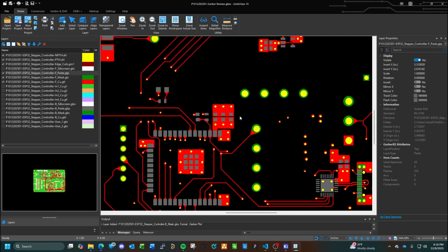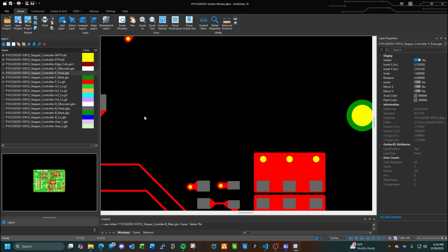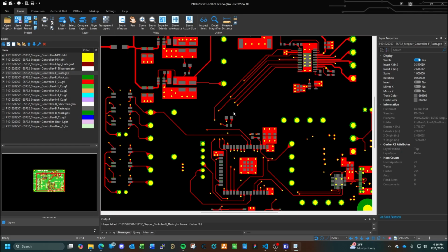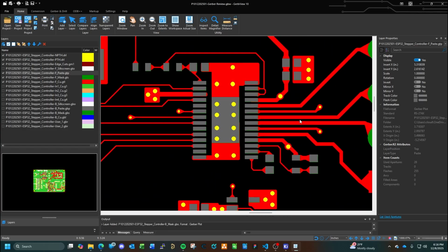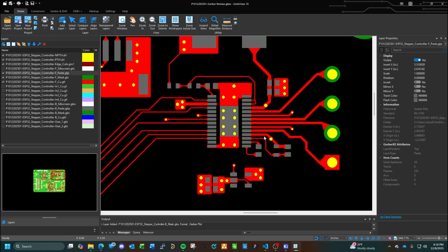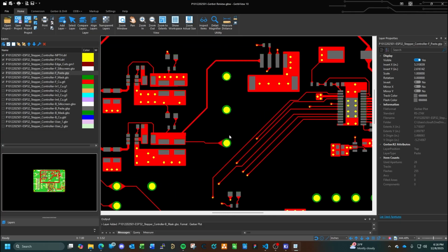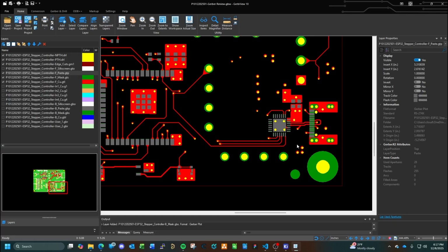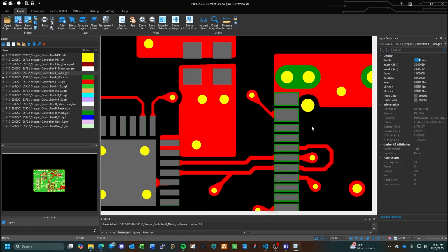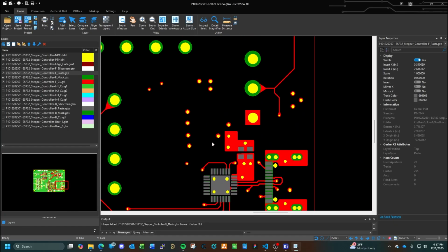So when you get the stencil, it'll be basically a flat sheet of metal. Think of it like really thin sheet metal, and these are going to be laser cut openings. That's where the paste is going to be placed. For those who've never really worked with PCB stencils, I'll get images and video when we actually go to build. Like I said, I have a webcam and we're going to do some actual video of the process, so you know what's all involved. We're going to be hand assembling. You'll at least understand it.